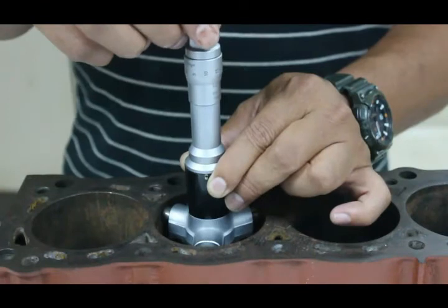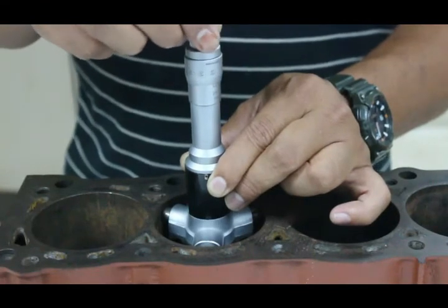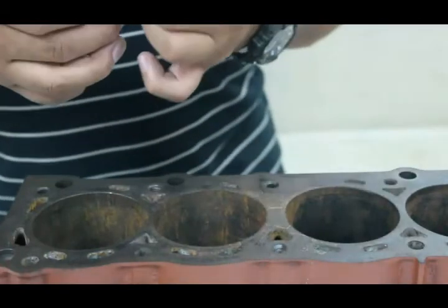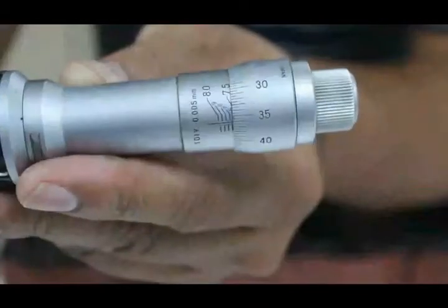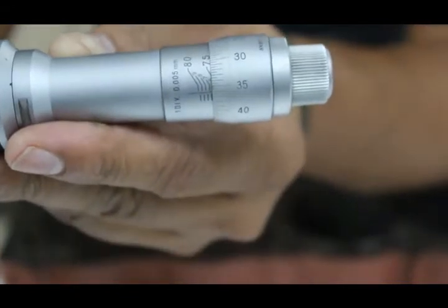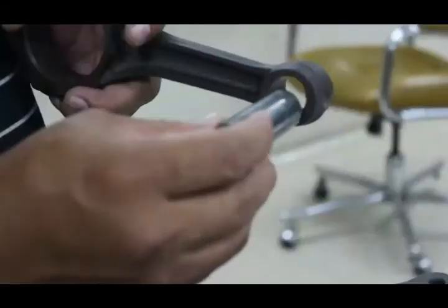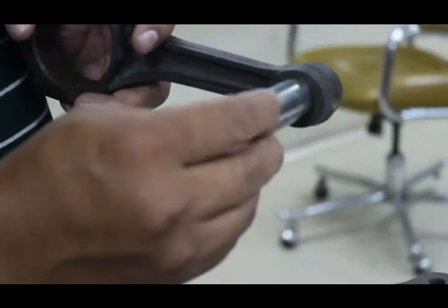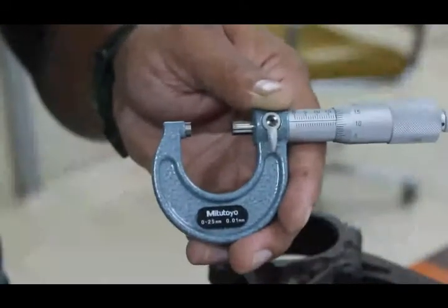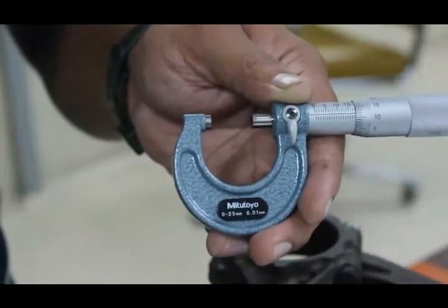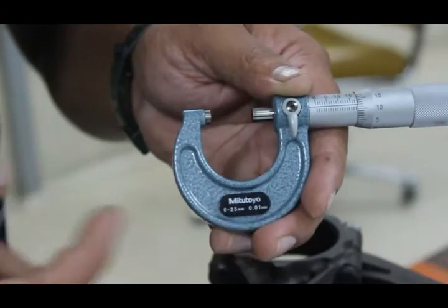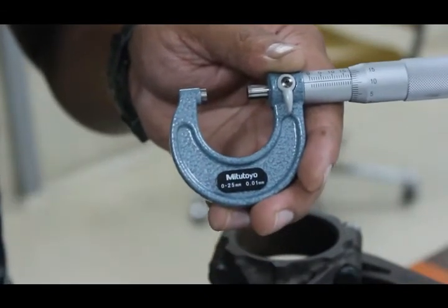For the inside and outside micrometers, students are exposed to the proper handling and use of the micrometer, as well as the calibration process. Students are given the ability to use both inside and outside micrometer and take measurements of an engine block as well as pistons and component parts, connecting rod and gudgeon pin. In addition, they are given the exposure whereby they understand the importance of calibration, zeroing of instruments, and the proper handling and use of micrometers both inside and outside micrometer.